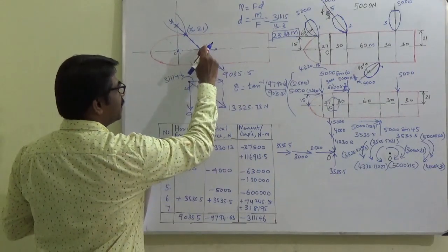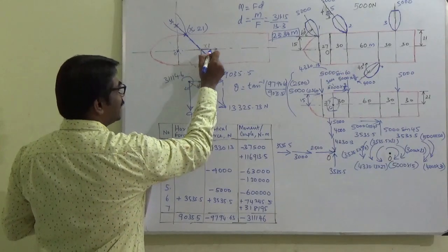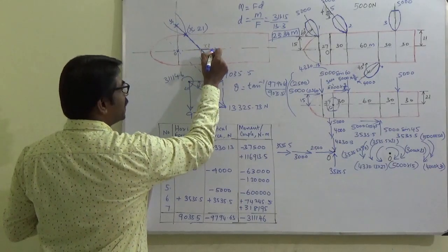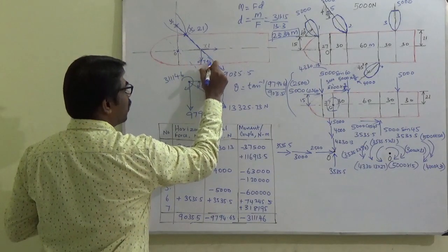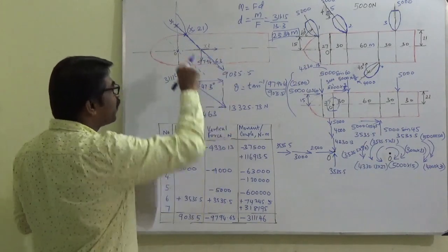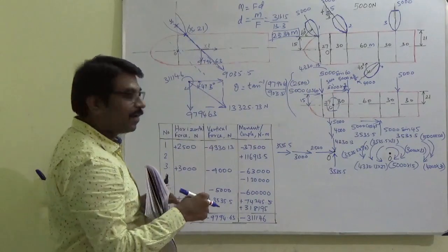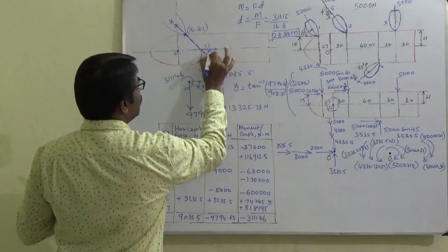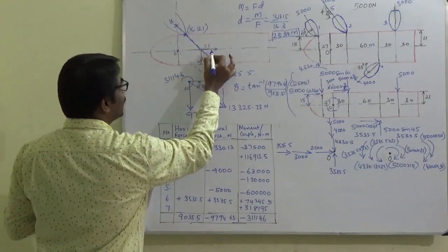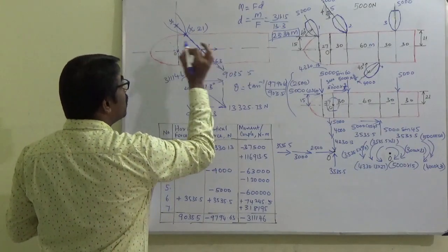these two forces here towards right, the x component will not produce a moment. The y component 9794.63 will contribute for the couple, and it will produce a clockwise couple. So the x component will not participate because it is passing through O. It will not produce a moment.